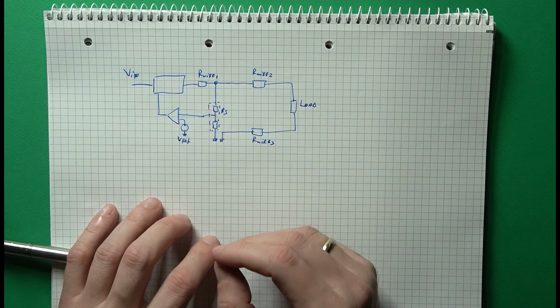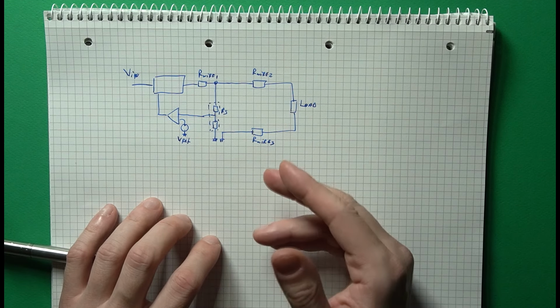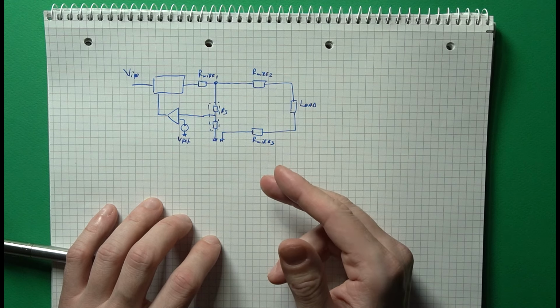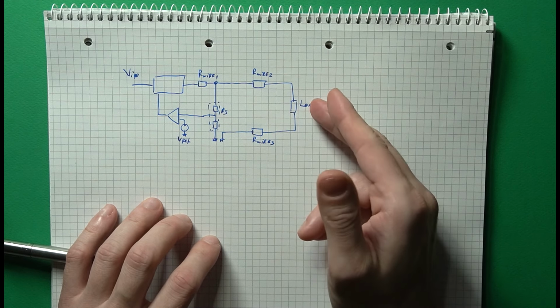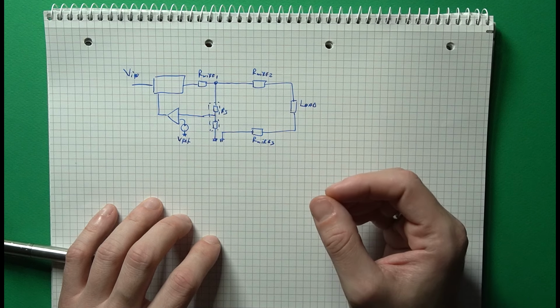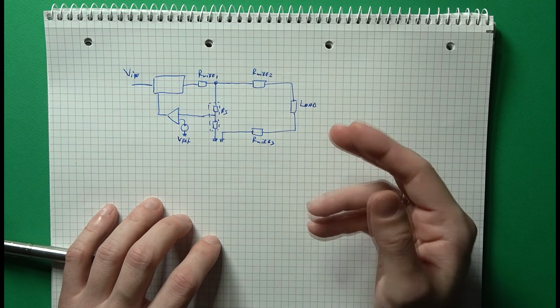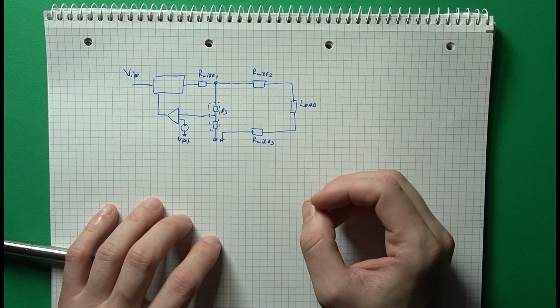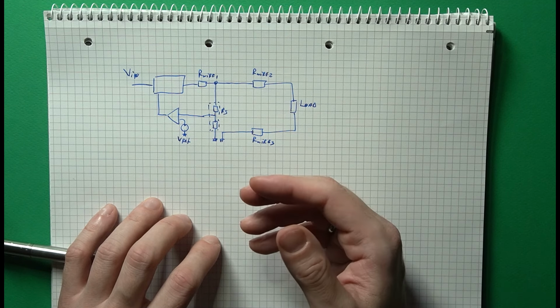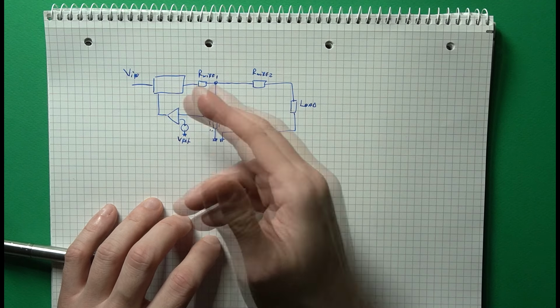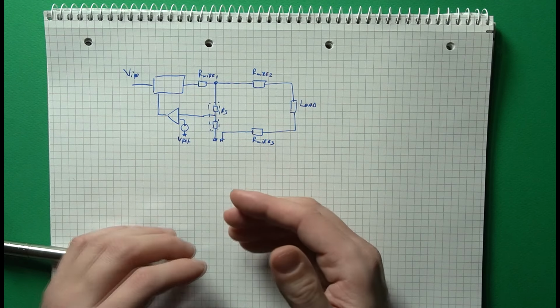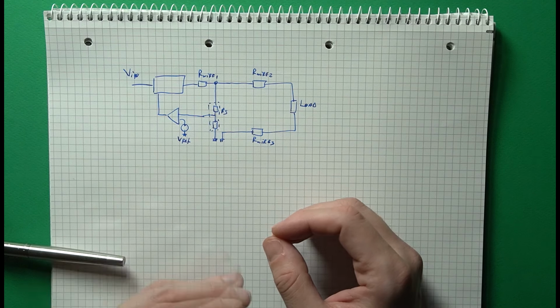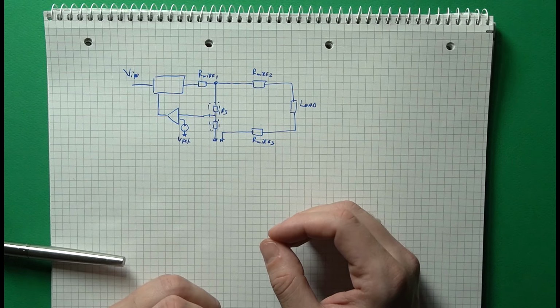Now, the measurement point is also important to observe, since in the real world, the trace between the power supply and the load has a finite value of resistance. In other words, the higher the current that is pulled by the load, the lower the voltage that arrives. This will apply regardless of whether the sensing is built into an integrated circuit or is external, and is independent of the initial component tolerances.